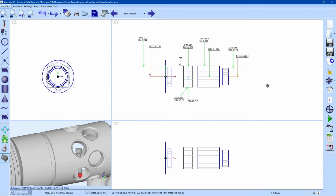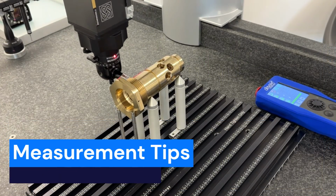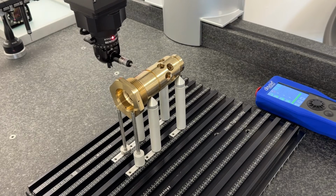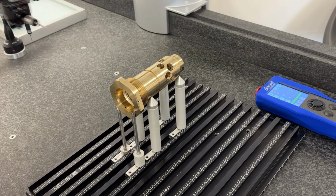So that is sort of the ideal world situation. We'll now look at setting up where we do the whole thing through concentricity. When we're measuring spindles or shafts, it's always worth remembering we want to try and take at least 15 points when measuring cylinders, at least 7 when measuring circles, and we need to try and measure the entire diameter.